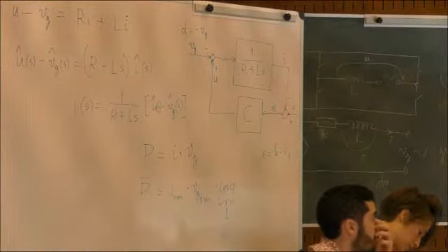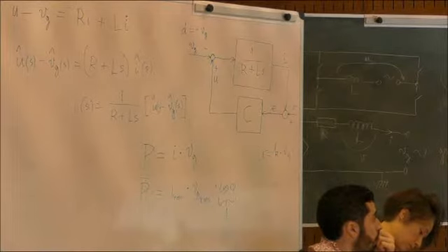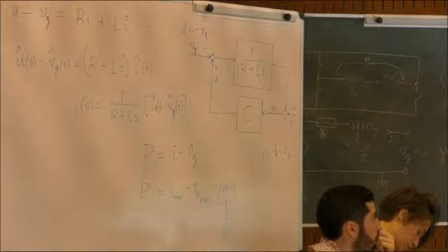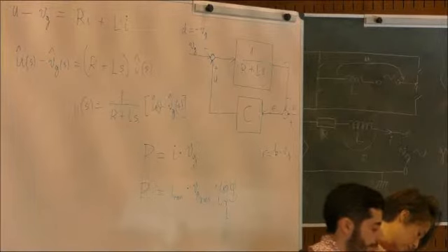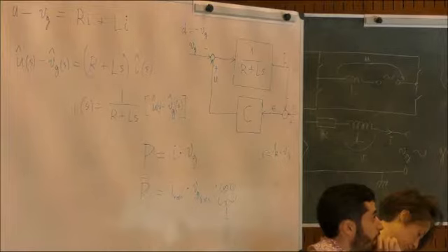So what does it mean too nonlinear? There is a measure for that. It's called the total harmonic distortion. You do the Fourier expansion of the current of a consumer. So it's a Fourier series of the current. Then you have a fundamental component, which is a component at the grid frequency, 50 Hertz. Yes? And then you have many more components, which are the distortion.